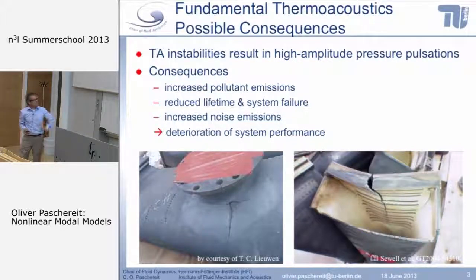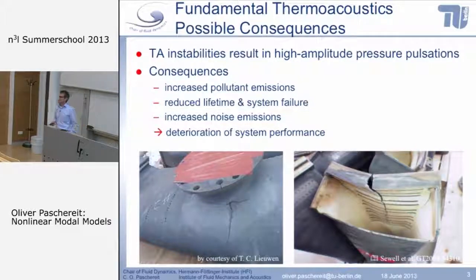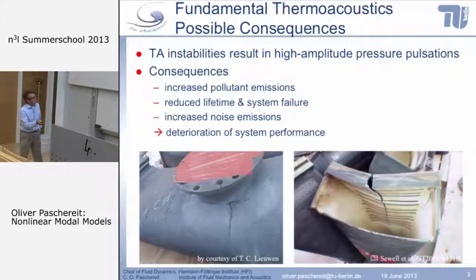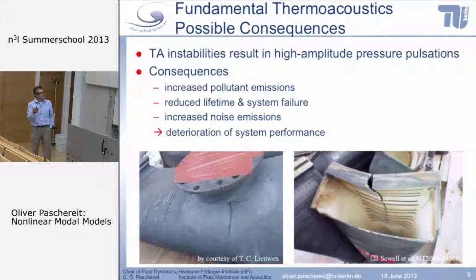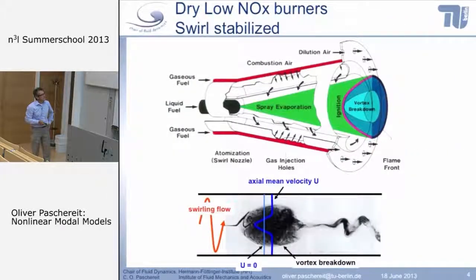And it actually increases with new gases. So if you go to hydrogen-rich fuels, the problem might increase, to syngases and so on. So the deterioration of the system performance is definitely an issue, although system failures due to combustor damages are obviously not occurring that much with the understanding we have today.